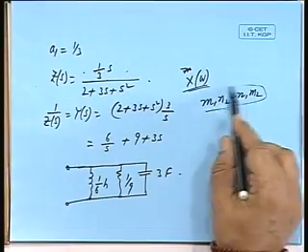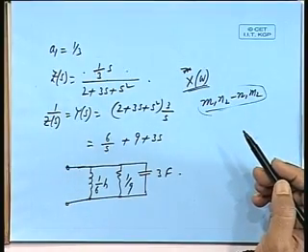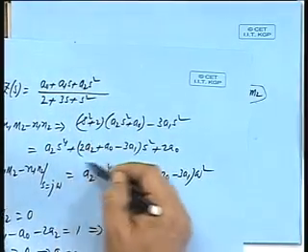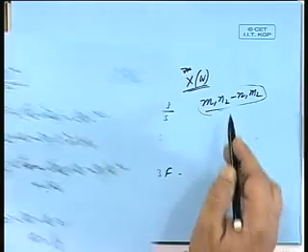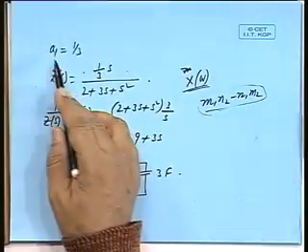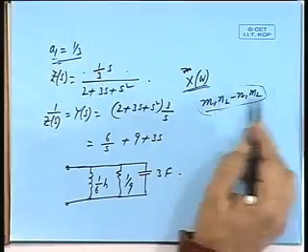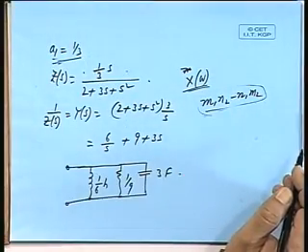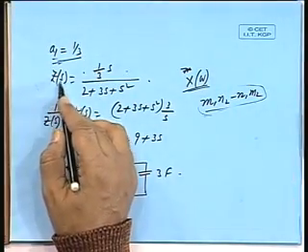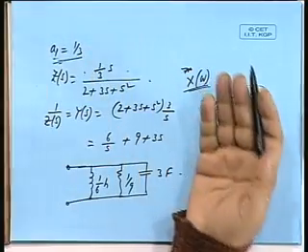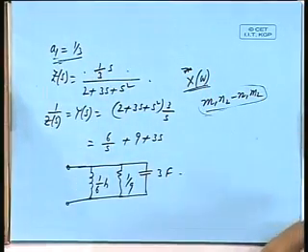M2 square minus n2 square is already known, that is 1 plus omega to the power 6 and so on. So it is this part which has to be computed, from a0 a1 a2 you can calculate this and substitute. Once you have calculated these coefficients, just substitute there, you will get the odd part. Otherwise in Zs put s equal to j omega, take out the real part and the imaginary part, that will be giving you X, okay.